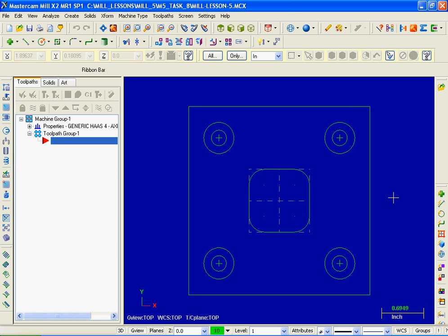In this video I will create the four 2.25 radius arcs. These four arcs are tangent to the 0.25 radius circles. I'm going to use a couple of different methods to create these arcs: arc tangent and the fillet function.